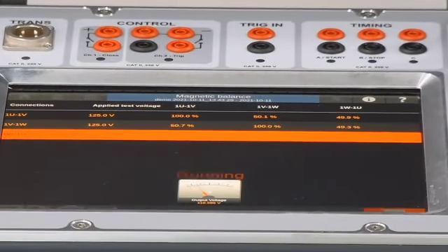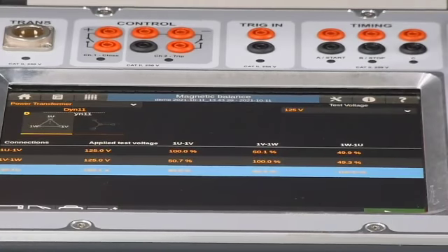So I expect also to have the same result as the first phase. I have 50-50 on all while applying 100 on each phase, which is considered maybe a good result for this type of transformer. You can also make sure that you have run demagnetization before this test, and this is to prove it. Of course, this is only to show you the way we are doing it, and we are happy with this result.